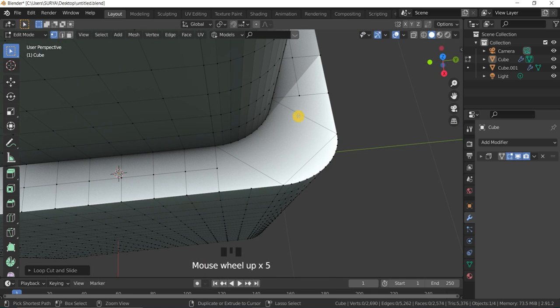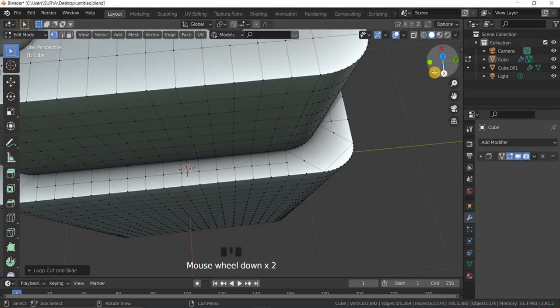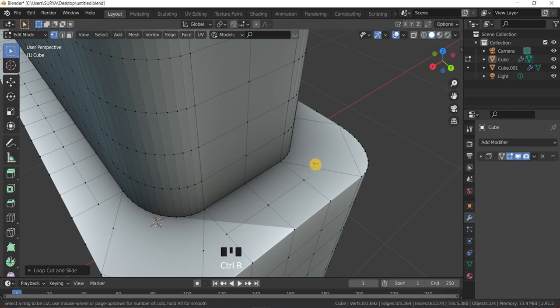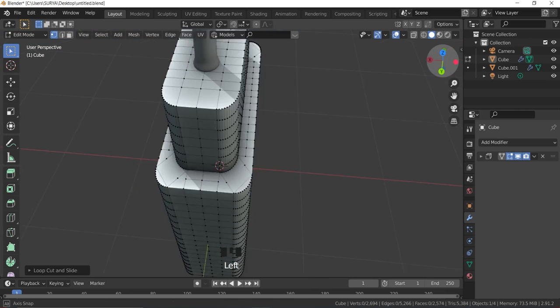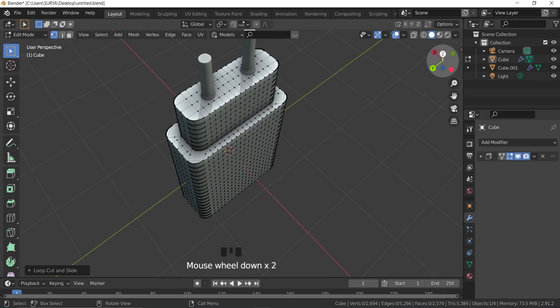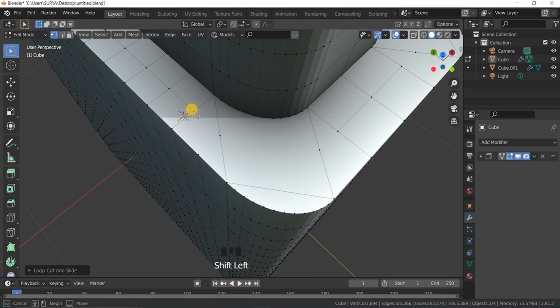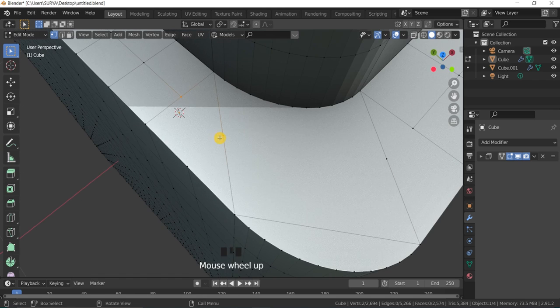It is also helpful, I will tell you. First create the loop cuts. The points are assigned by using Ctrl R. Then I want to intersect all of the edges by selecting, for example, the first point, second point, and going to the connect vertex path.